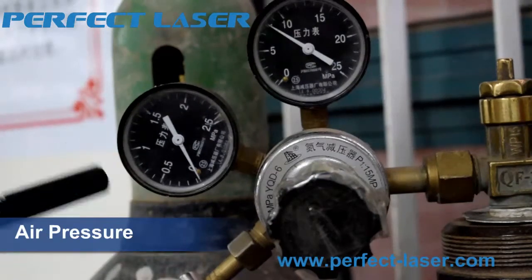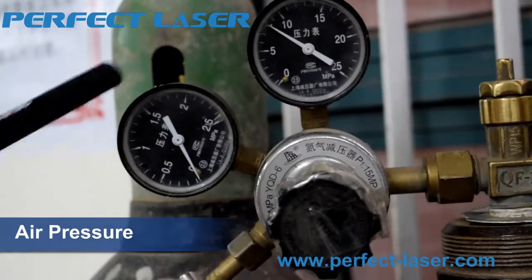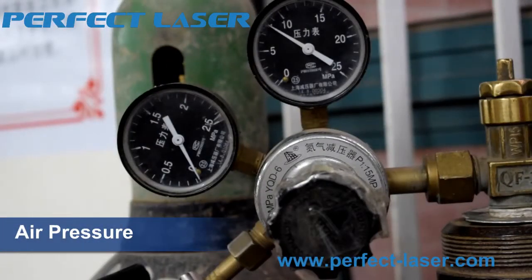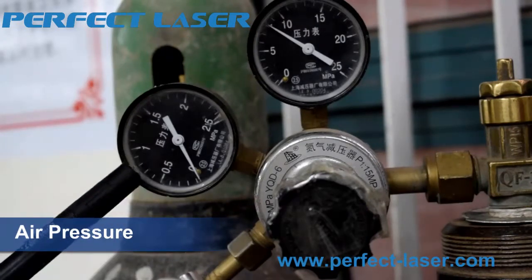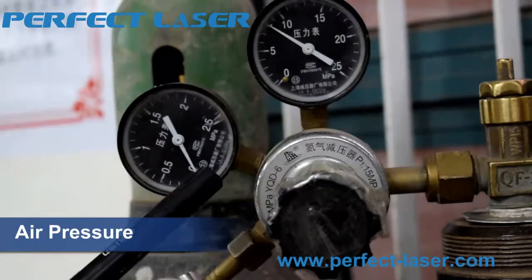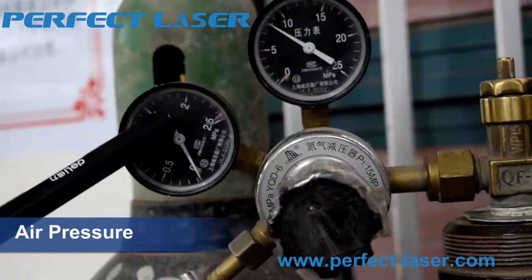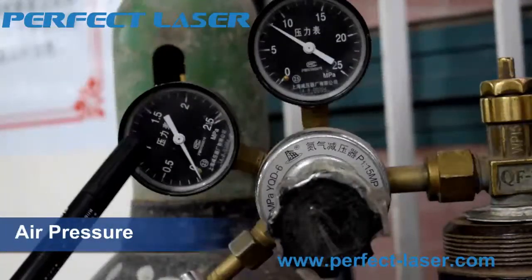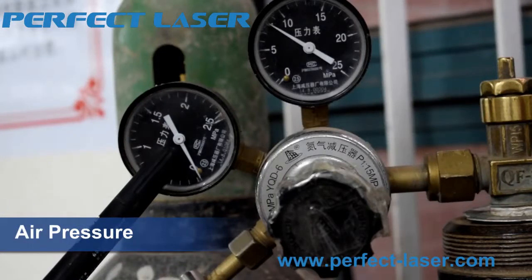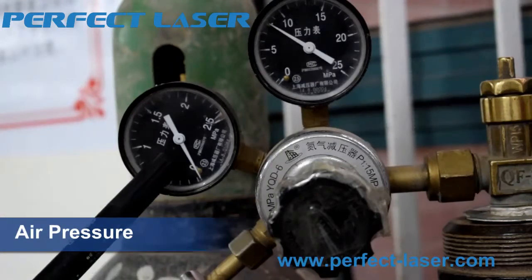as you can see, the gas pressure indicator, this is to indicate the power supply for the machine. Usually, the gas pressure should be 1. That means it should be indicated to 1 MPa. If the gas pressure is so low, it will have a huge influence on the cutting effect. But